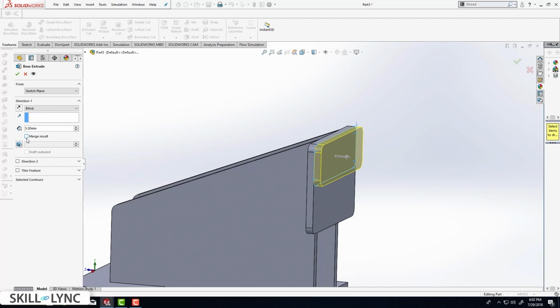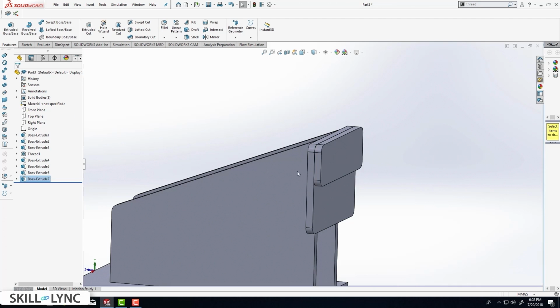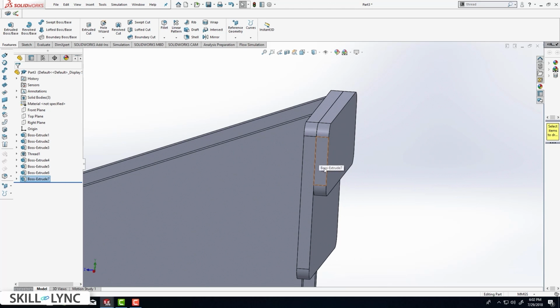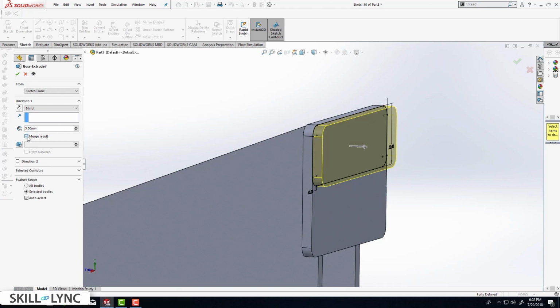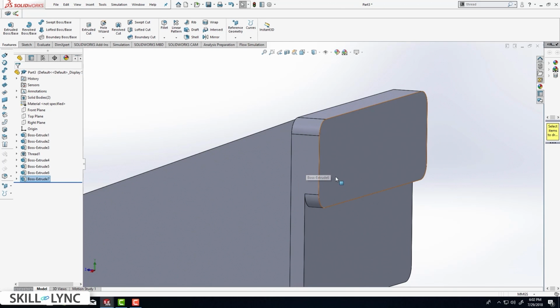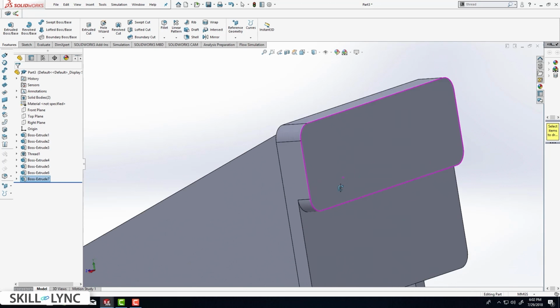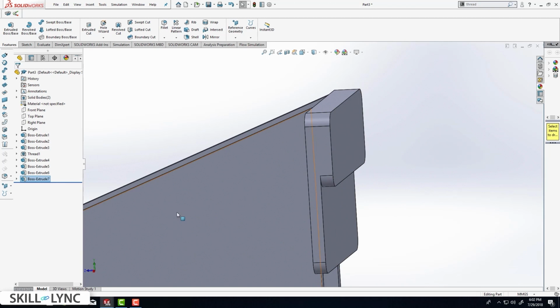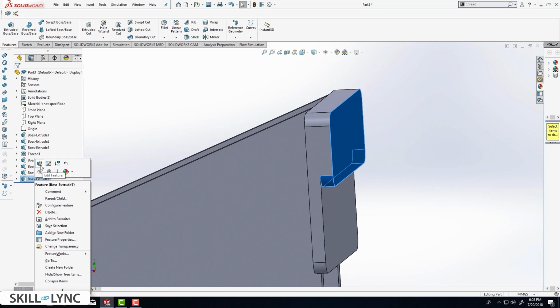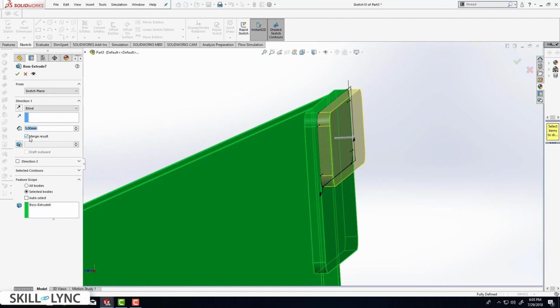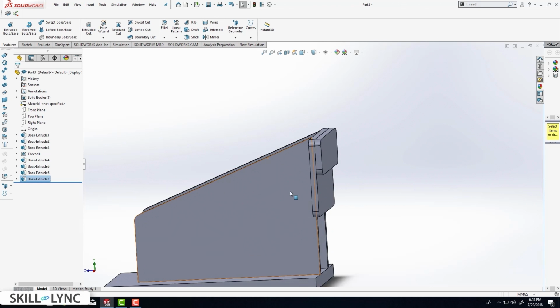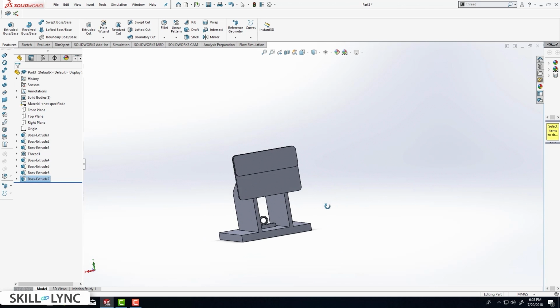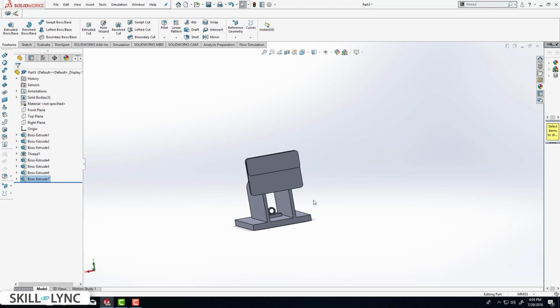result is not selected. Why are we doing this? When you do this, you will be creating 2 separate solids. So now if you click on edit feature and if you click on merge results, you will see that now it's a single solid, right? So this is the difference between using the merge result option and not using it, basically. So we are going to uncheck the merge results so that we are going to have separate solids in this particular case. So now we are ready to save this particular component, right?